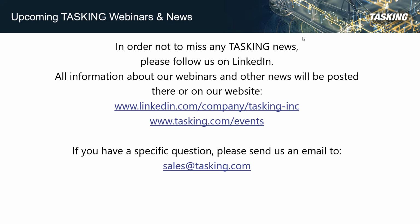We have another webinar planned for the second half of this year, which will go into much more detail regarding the cache, the program P cache and the D cache. But just to answer your question, if you think that you have a data cache miss or a program flash cache miss, that can also be detected using the embedded profiler. When you run profiling, it will show you if you have some data cache or P flash misses. Thank you, Bharat, for answering this question.